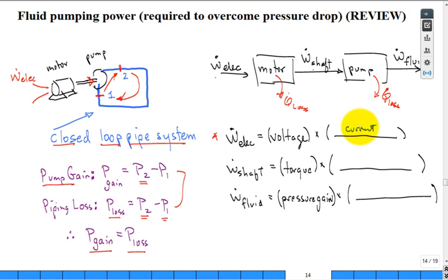Now, if it's 3-phase, there's a factor. Does anybody remember? Square root of 3 it is. And if you have to work with 3-phase power, you'll have to deal with that one. And this is the RMS current and the RMS voltage. And there's also a PF, a power factor. So life isn't as easy as this, but this is the basic idea. It only gets worse. All right.